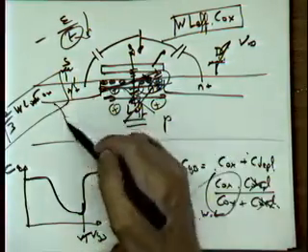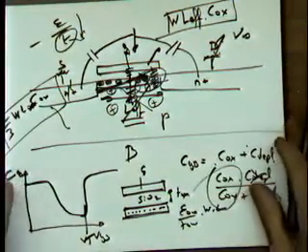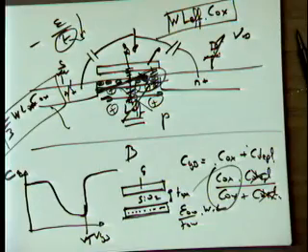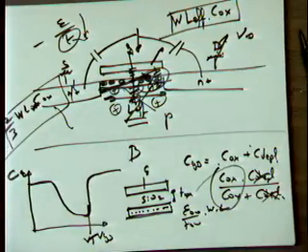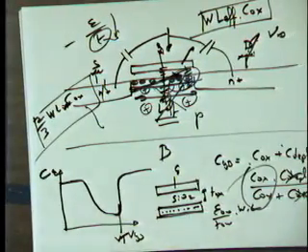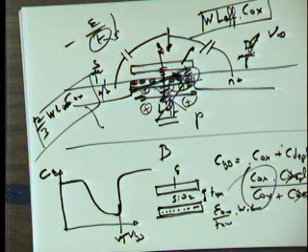If you actually work out the equation, you see it's perfectly correct, but it's not something you can explain intuitively. You really have to work through the analysis of the capacitors, work out the charges in the channel, integrate them out, and you will figure out that the 2/3 actually is the right answer. So there's no capacitance anymore to drain at that point when you go into saturation.